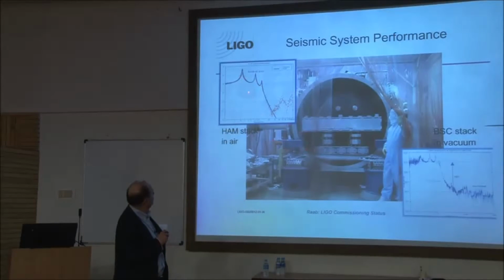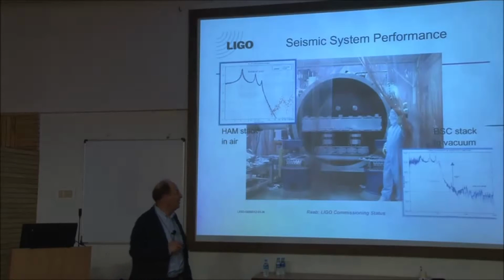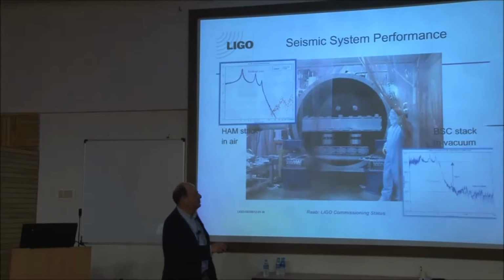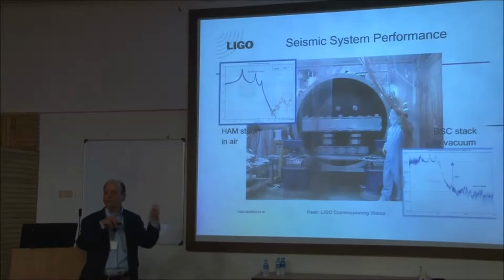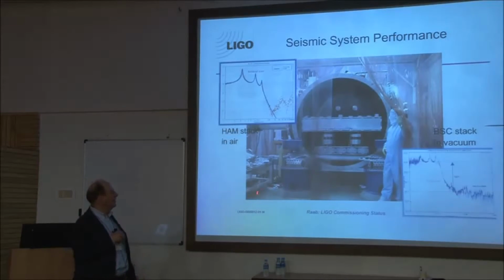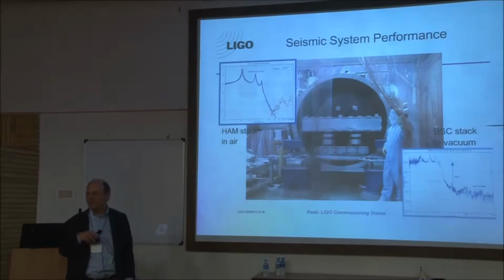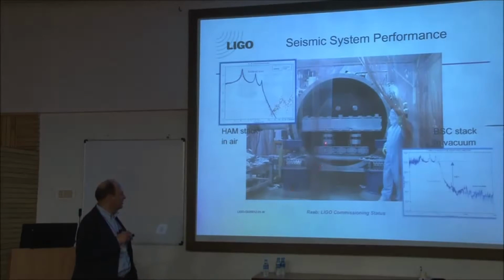And here is the frequency response as measured in air for this isolation system. And you see 3 resonances for spring mass, spring mass, spring mass. And then you see isolation falling pretty steeply, as you'd expect. And then you see all this junk, which we're pretty sure was not a failure of the frequency response of the system. It wasn't that effect, but this was acoustic short-circuiting of the measurement. It was the driver making so much noise that it directly shook the most isolated part, rather than sending a mechanical vibration through the metal parts.